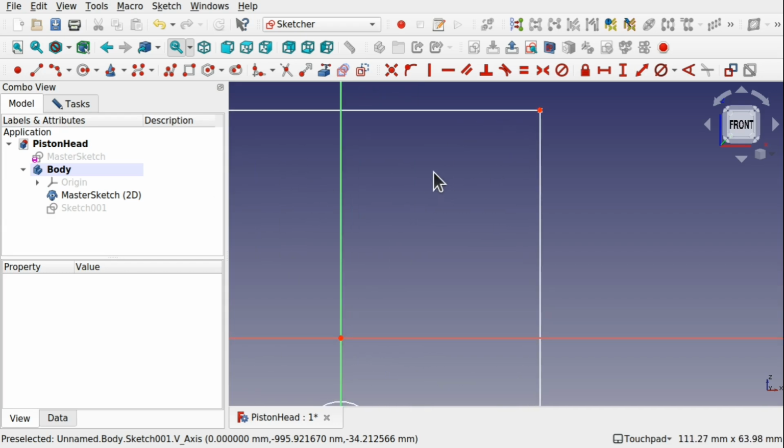So we've got a number of sealant rings, we've got a wiper ring and an oil ring that goes around here, and they're all connected into a groove that goes along here. So I'm going to create these grooves. I'm going to use the create a polyline, and we're going to start sketching from the center. We only need one side because it's going to revolve right the way around this line here, and we can connect up to here. See, it's gone green.